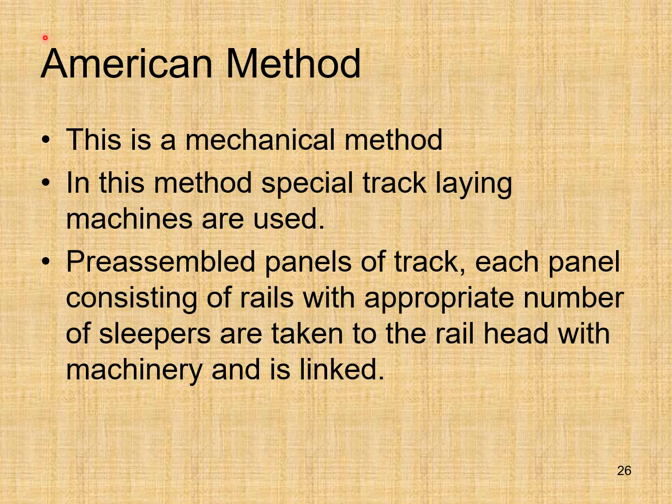Now look at the American method. This method is basically a mechanical method. In this method, special track link machines are used. Pre-assembled panels of track, each panel consisting of rails with appropriate number of sleepers, are taken to the railhead with machinery and linked.